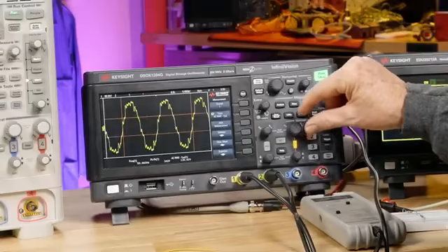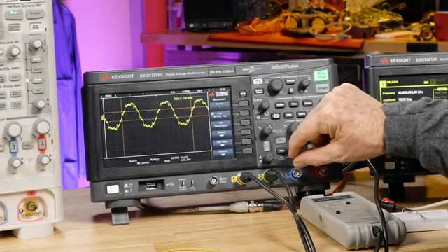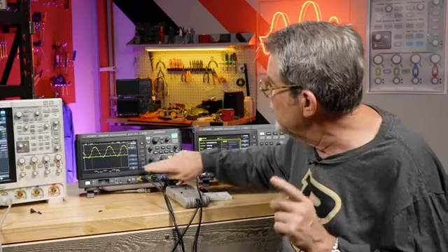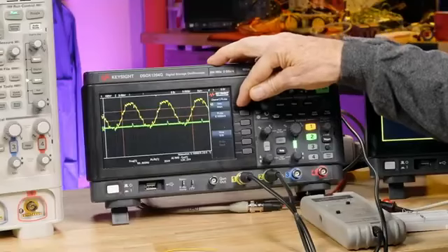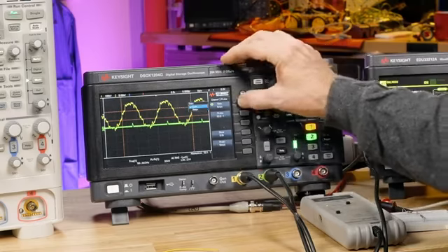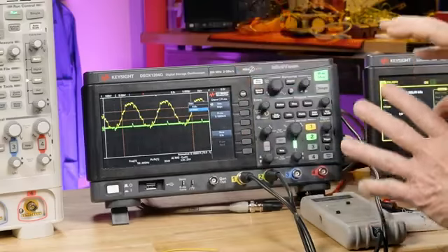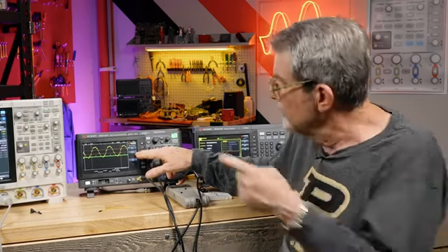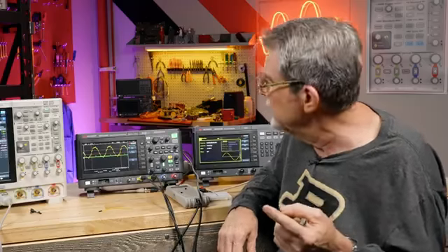Let's look at the current waveform. I'm going to rescale this first, move it up here, so we can separate the two. Turn on the current. Now I have to do the same thing. Go into the probe menu, and normally it comes up in volts. If I select amps, now it knows it's measuring current, so it's going to convert voltage to current. And instead of a probe attenuation factor, it has a conversion factor. In this case, I'm going to use the default 0.1 volts per amp. That's the conversion factor. That's pretty much equivalent to a 10:1 attenuation.